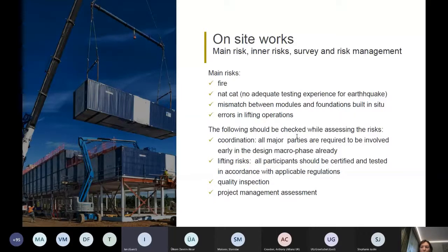If we speak a little bit more in detail about these risks, there is again a difference between modular and traditional construction. In respect of fire, in modules we do use more combustible materials like polyurethane, sometimes plywood, sometimes timber. So all of these are combustible. The second issue, which is important for fire risk, is compartmentation. With modules, there could be some problem, because modules are sometimes not very close to one another. There are slight gaps between them, but for fire it's quite enough, so the fire can spread very quickly through these gaps, and this could lead to a rather big loss.